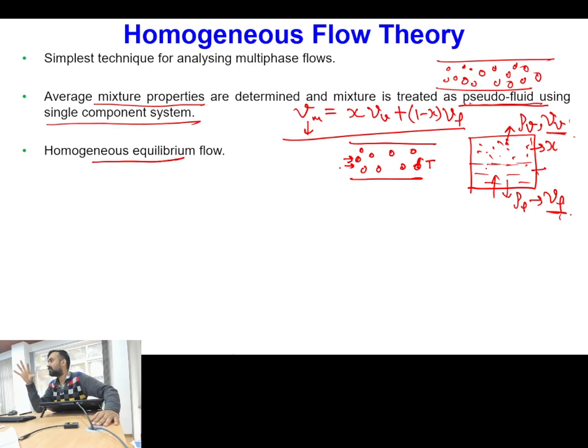If we are going with that much of an error range, then even for many multi-phase flow situations we can obtain the analysis of the system using this assumption with an accuracy of 20 or 25%. That is a reasonable accuracy for starting with practical systems. So that's why we can still continue with this theory.